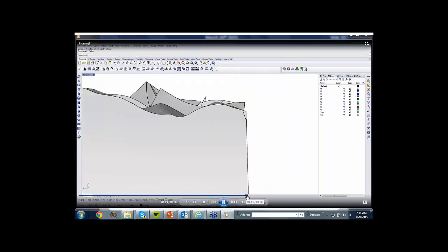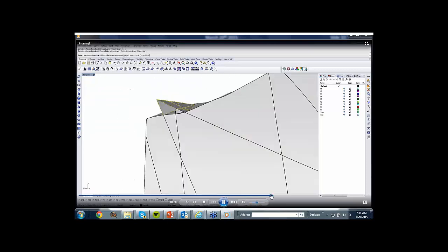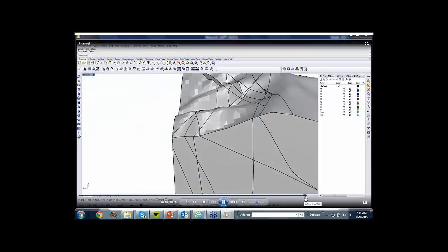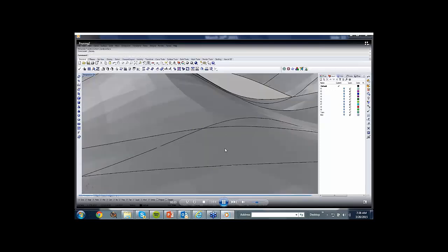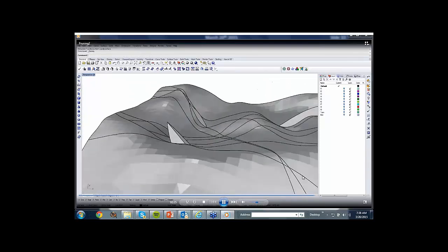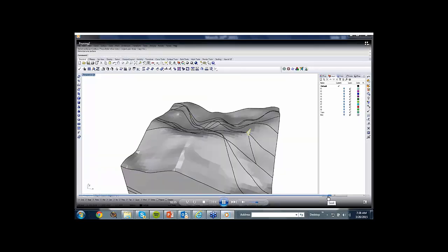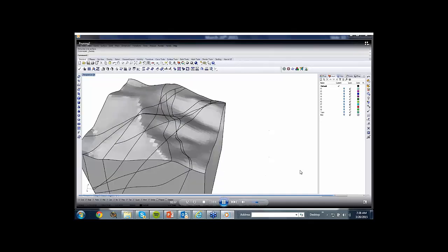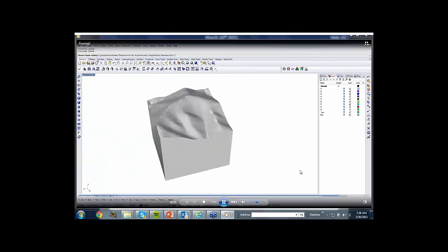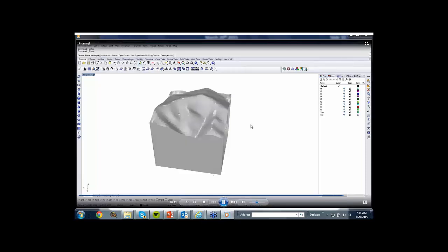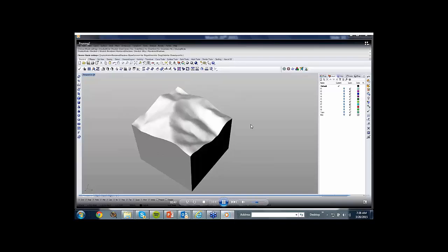So I keep on removing all these other bits of surfaces that stick out. Just remember that sometimes it becomes very hard to see, and I think one good way of doing that is to use the various shading functions that are available within Rhino. You know, this becomes complicated at some point. So I'm using the flat shading, then I'm going to go into some sort of a shaded rendering here. That is a good way to see